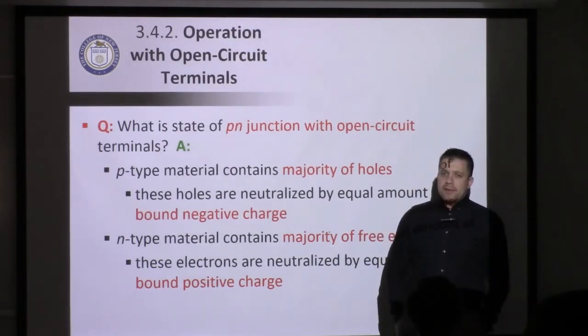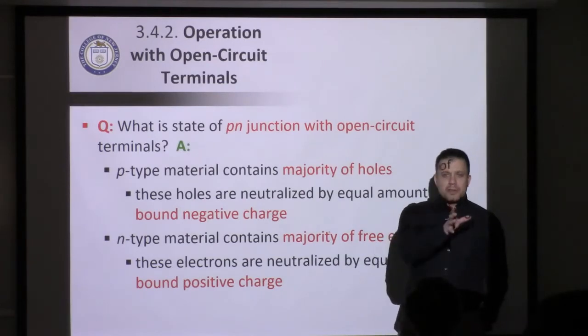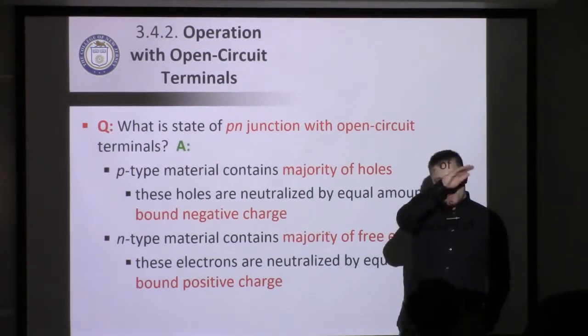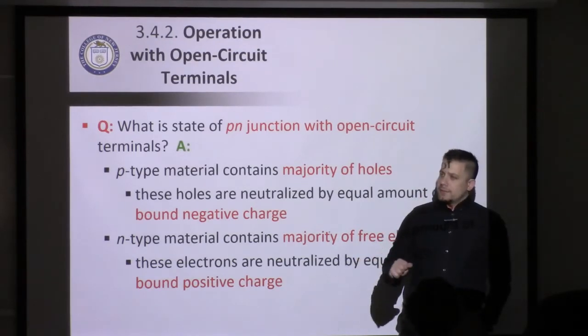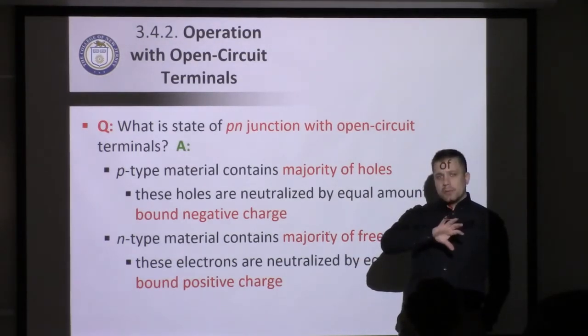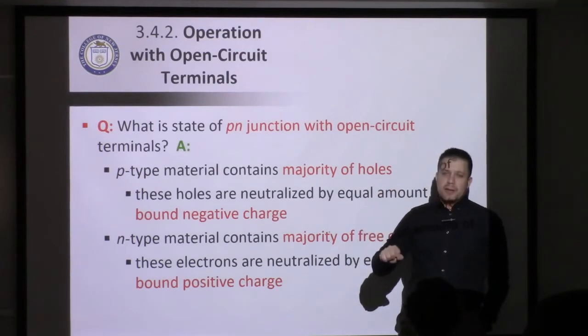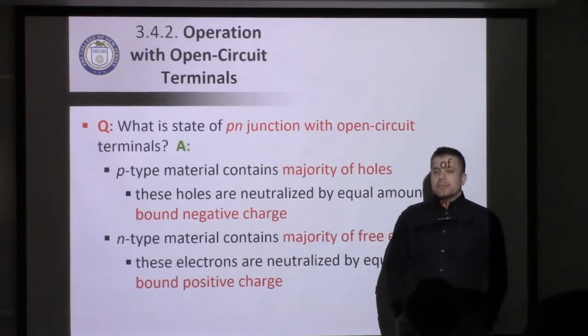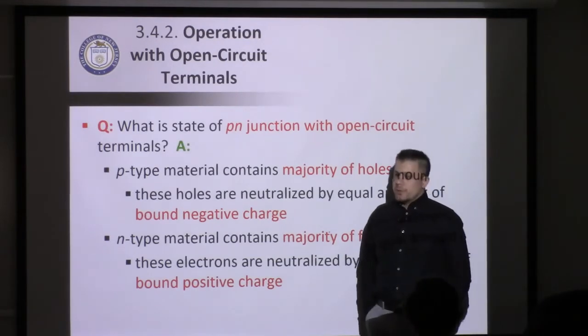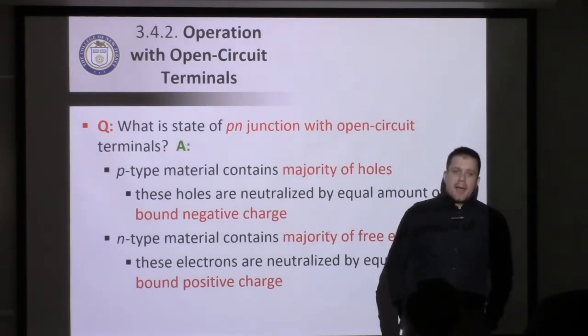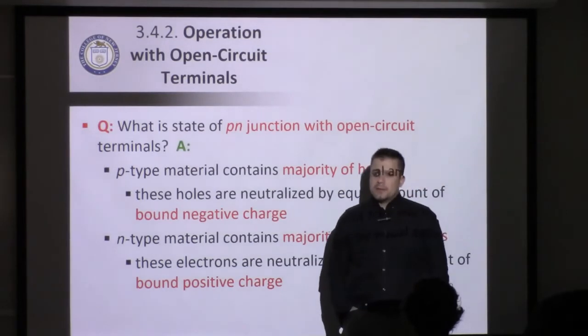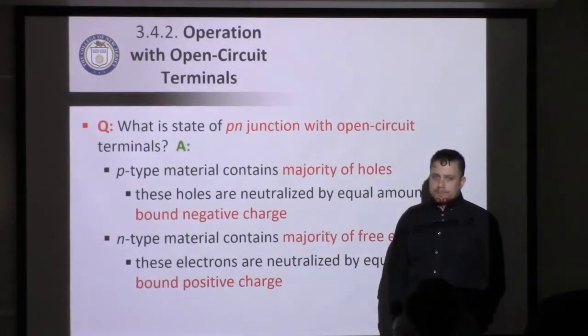So what we have is a whole bunch of free electrons on one side, very few on the other side. We have a large gradient, and so a diffusion force will push the charge carriers to even out that concentration gradient. So drift current, diffusion current, we talked about both of them last time, and we'll see that they both come into play when we talk about the structure and the operation of a pn-Junction.